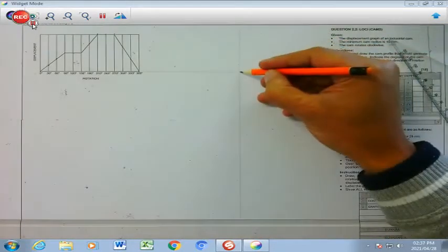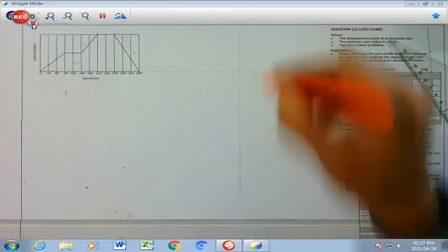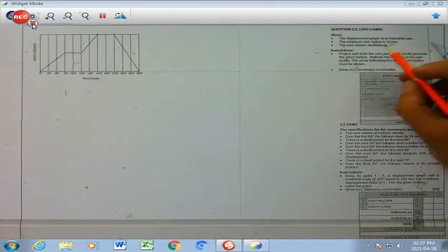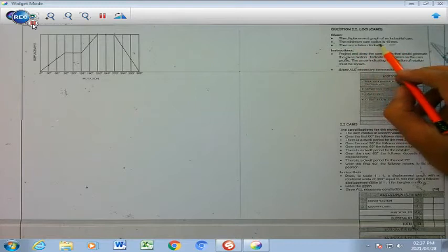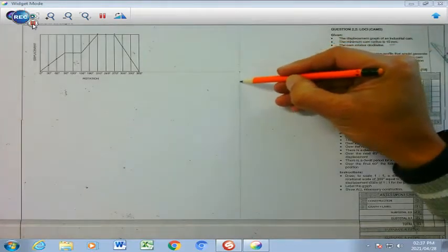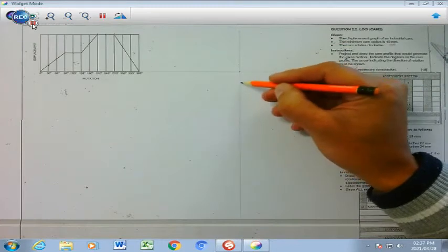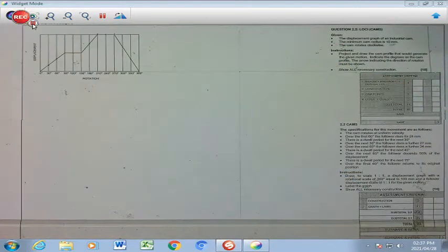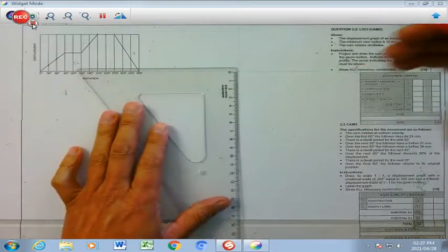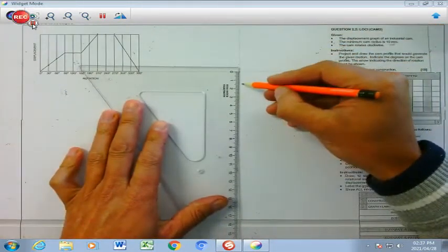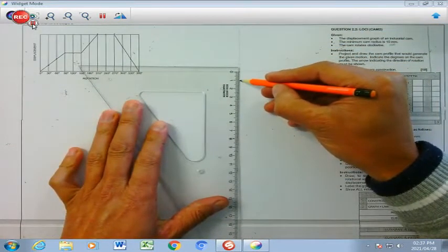And this point is going to be important at this stage because I need to use my minimum radius from here down. So minimum radius means that I must be able to draw a circle in here with a center that's there. So I'm going to measure 10 millimeter radius down. So there is going to be my 10.